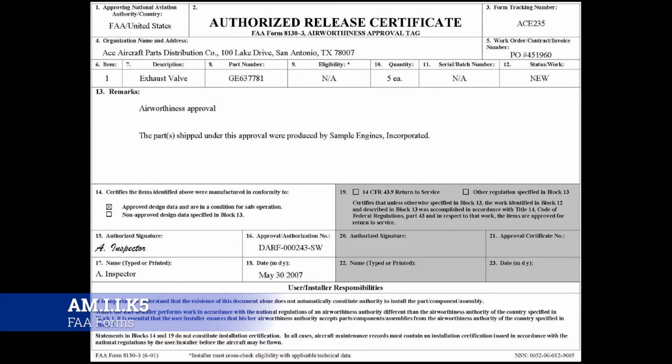The more realistic situation is that it comes with a part, and you have to take this and you have to maintain it. Sometimes these are just kind of formalities that once you get the part, especially if it's some sort of consumable type part, maybe you don't need to keep up with it as much. But most of the time, whenever you get a part in, this is going to go in a logbook. The Learjet has like 2 or 3 massive folders full of all of these 8130s. Here's 2 of them in the sleeve that I pulled out just as an example.